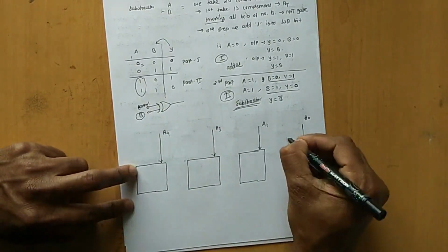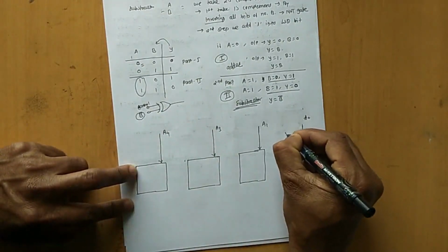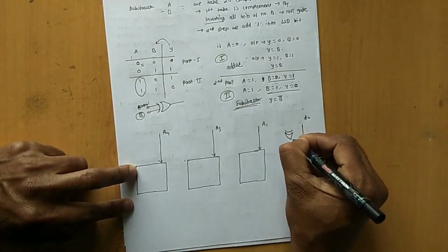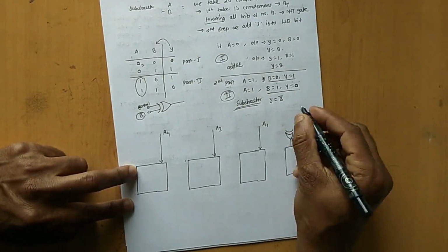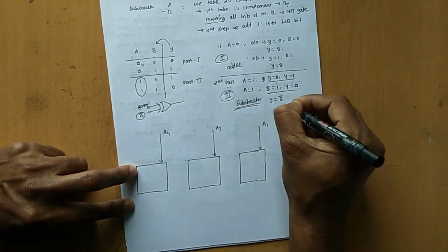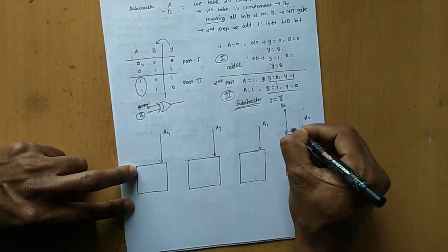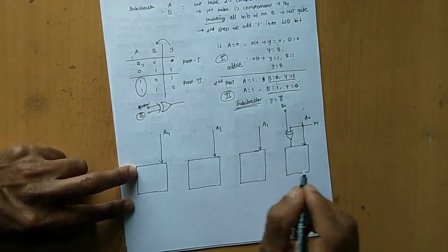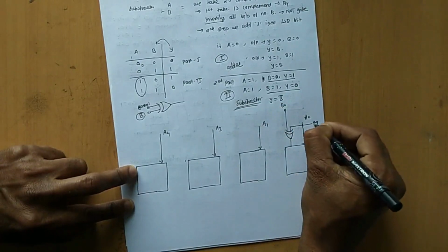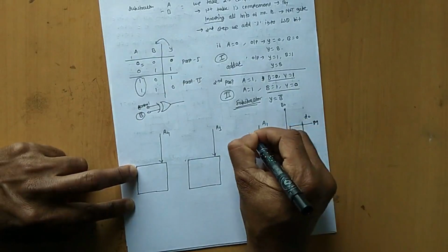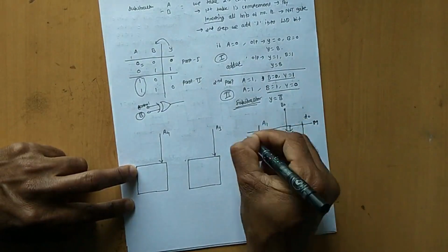So we have to take first an exclusive OR gate, with two inputs. One is the number B, B0, and another is M, that is a control input, M. This will continue with the second full adder also.